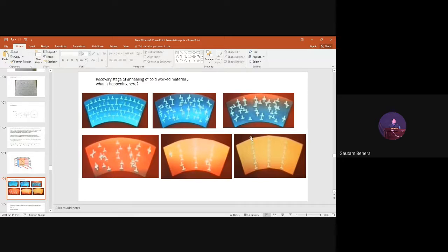Everybody can see all are like dislocations. So unlike dislocations are getting annihilated during recovery, but like dislocations are arranging themselves in a particular fashion. They are arranging one below another, right? It is clear now. This is called polygonization, if you remember. How many of you have remembered polygonization? Nobody has remembered this term?